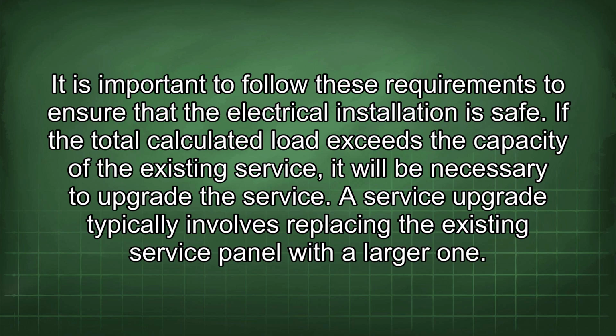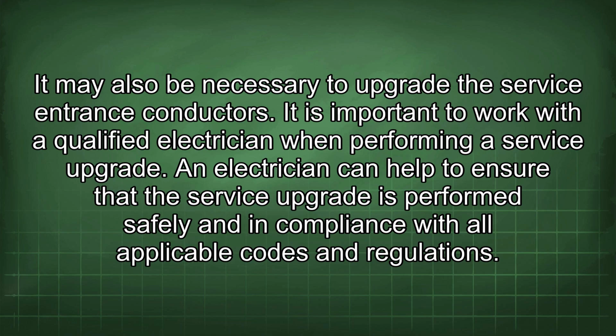If the total calculated load exceeds the capacity of the existing service, it will be necessary to upgrade the service. A service upgrade typically involves replacing the existing service panel with a larger one. It may also be necessary to upgrade the service entrance conductors. It is important to work with a qualified electrician when performing a service upgrade. An electrician can help to ensure that the service upgrade is performed safely and in compliance with all applicable codes and regulations.